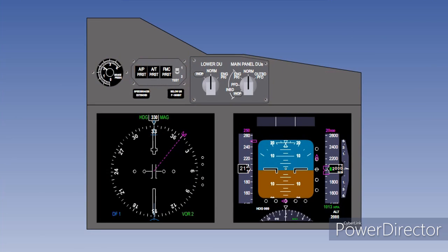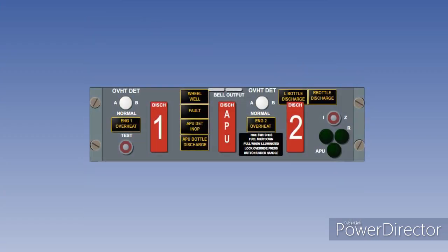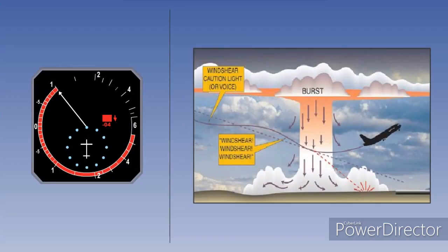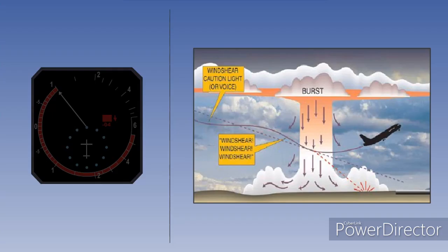On Airbus aircraft, a continuous repetitive chime accompanies all level 3 alerts, and a cavalry charge sound is used for autopilot disconnects. In both types of aeroplanes, synthetic voices are used for traffic alert and collision avoidance systems, "Monitor vertical speed," and ground proximity warning systems, "Wind shear, wind shear, wind shear."